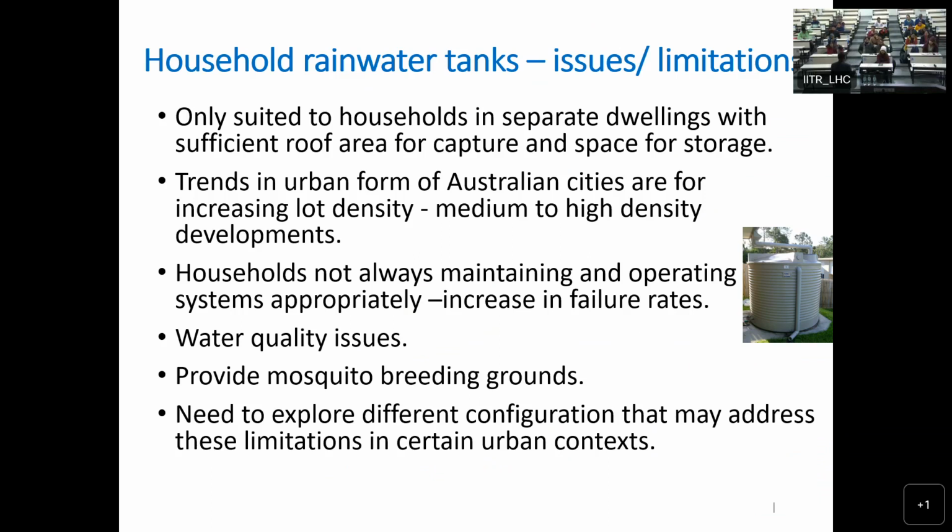You can develop your own Excel sheet, and then you can use rainfall for a couple of years, because you don't rely on 1 year of rainfall data. You should look at 5 to 10 years of rainfall data. I'm also sharing with you 10-year climate data for Malcolm. It's daily rainfall and temperature, and evaporation. These are the 3 parameters that we need.